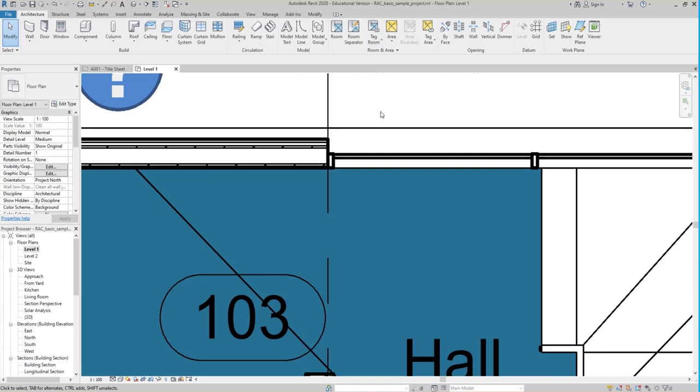If you're thinking of things in terms of importance here, I would say that the very first and most important thing in a set of drawings that graphically will be the heaviest will be the walls. Okay, so walls will be heaviest, doors and windows will be the next heaviest. So if we were going to define pen weights, we would say the walls are heavy, the windows and doors are medium, and then things like stairs and furniture and plumbing fixtures, those would be light, okay? And then the flooring would be fine, all right?